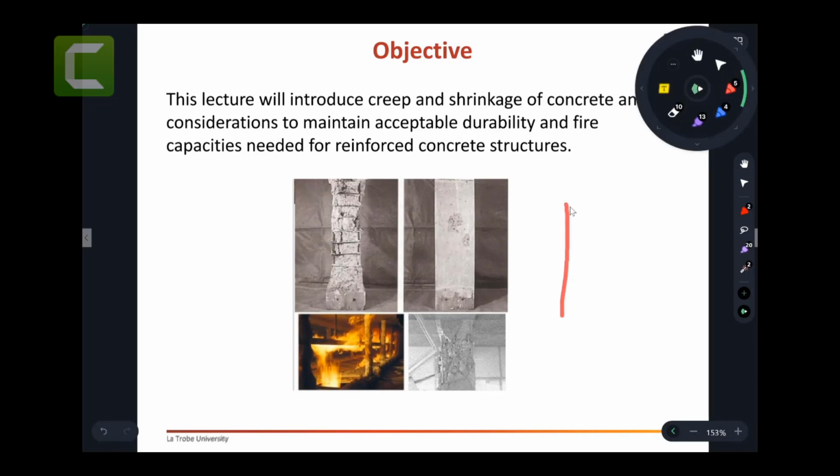So you're going to see next week one of the starting points to do our design. We will talk to you slowly about a cross section for reinforced concrete. This is it here, a rectangular cross section, and it's got a number of bars, for example some bars top and bottom. Now the key, the cover here, is the distance between the very top of your beam to the start of your bar. Same thing with the bottom, from here to there. This cover has a really strong impact on the strength, capacity, and deflection.